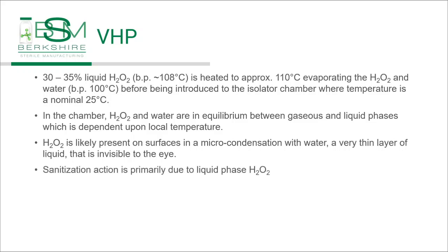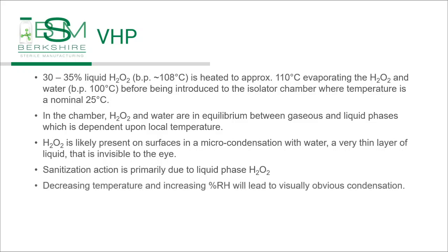The sanitization action is primarily due to liquid phase hydrogen peroxide, not gaseous hydrogen peroxide. Decreasing the temperature and increasing percent relative humidity will lead to visually obvious condensation. Higher temperature areas experience less sanitization action, because they can hold more water in the air at higher temperatures. So the percent relative humidity in those areas is actually lower, so you get less hydrogen peroxide put on the